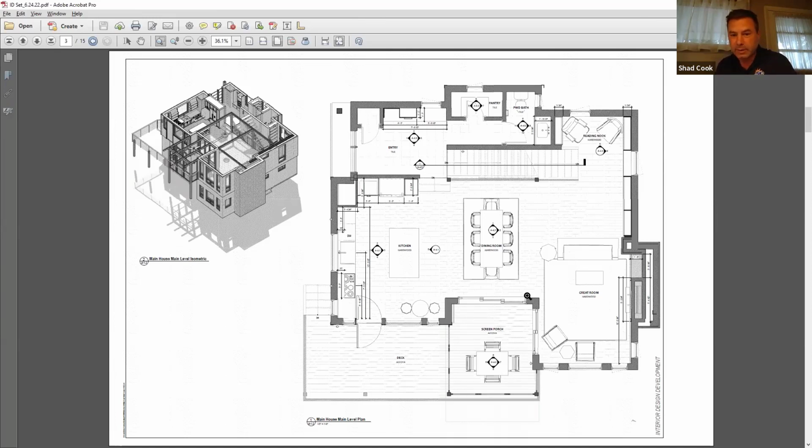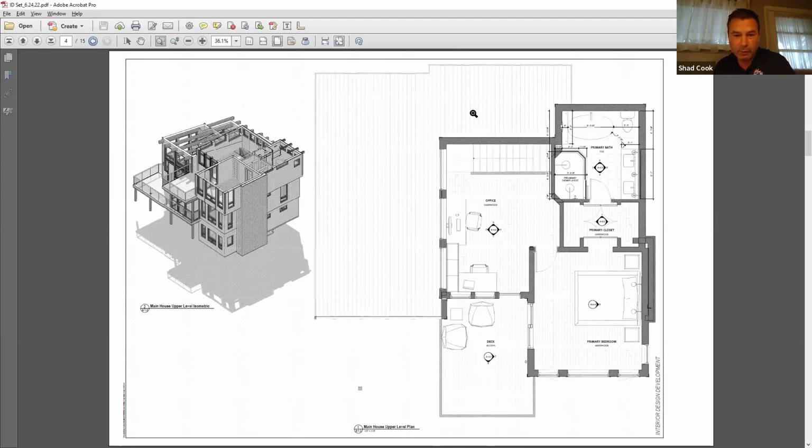Basically, that line right across there is where the framing is changing in the bedroom. So the joists go in one direction, and then they go a long way across the whole building once they pass that wall where that screen porch door is, correct? So if we were able to get into both of those areas, we can service something along the outside wall of the master bedroom, coming from a shaft on the bottom of the page side of that transition in the framing. And also with a shaft coming up where the joists are going across the building the long way side of that shaft.